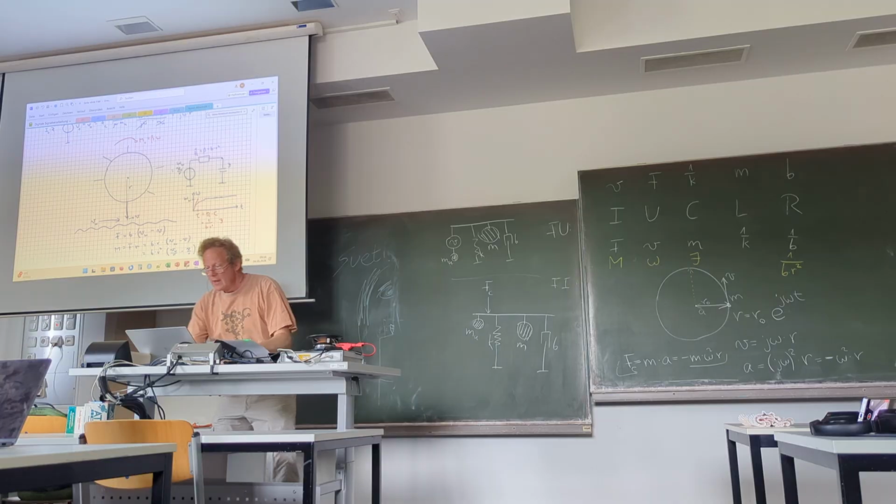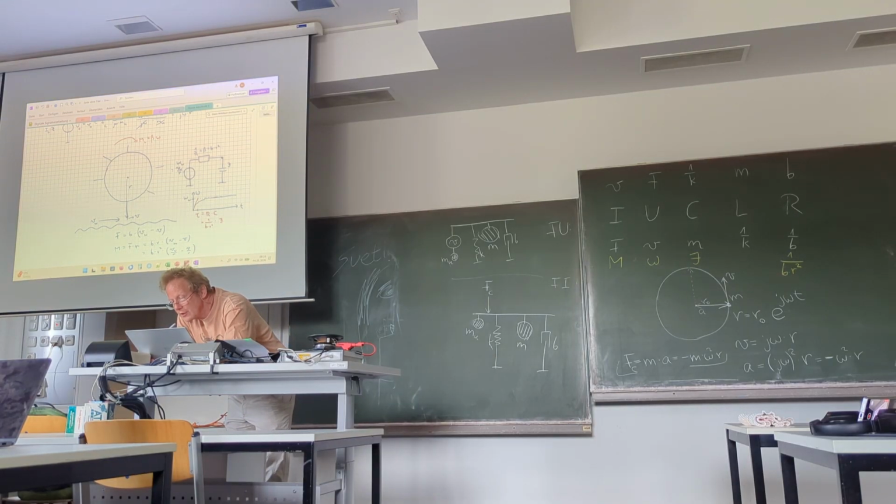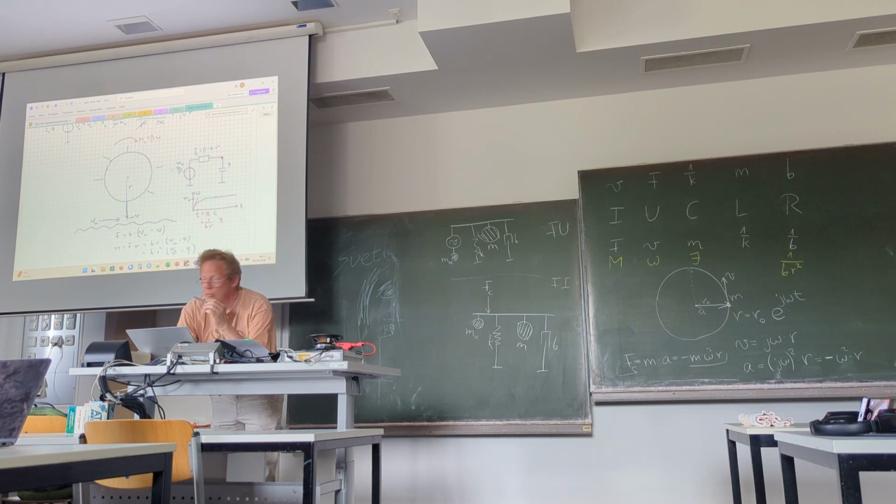And this somewhere is here our connection. This is our node. So here we have an additional current. It means an additional component. And because this moment is proportional to omega, or electrically, the current is proportional to the voltage, this component is a resistor. Of course, because we are talking about losses. Damping, B or beta, is always losses, and this always becomes a resistor.